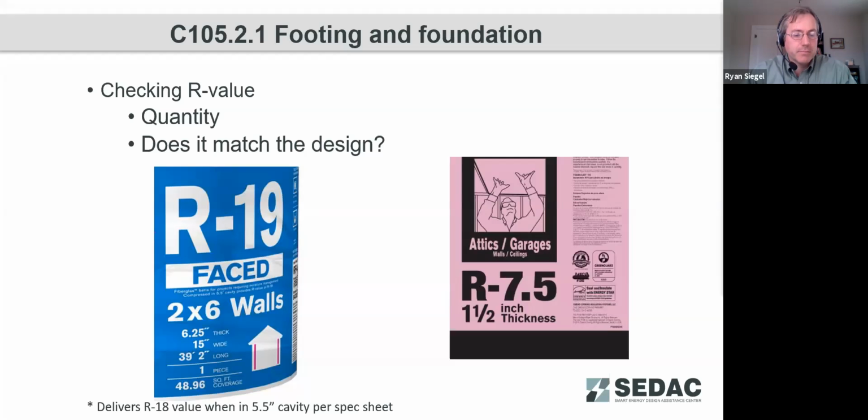As practitioners understand, a 2x6 is the nominal dimensions of the lumber. That is not the actual dimensions. 2x6 is typically along the lines of 1.5 inches by 5.5 inches.